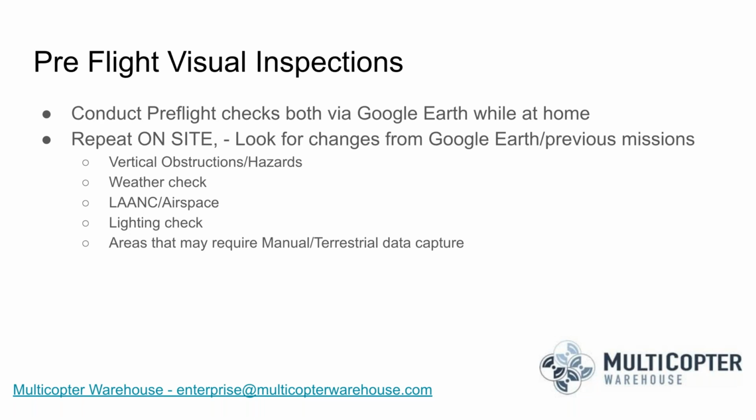You can use the gimbal knob on the controller to adjust the camera angle, but then the app will actually move it back down. So I think that using a point of interest flight mode within DJI Go or Go 4 and setting my drone to capture an image every 2 or 3 seconds as it's orbiting around is my preferred way to run an orbital mission using the Go app versus the Pix4D capture application.